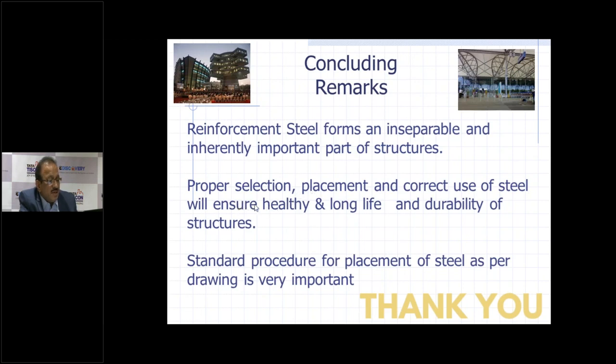Pushkar Patel wants to know, can we weld the bars instead of couplers? No, I will not recommend welding of the bars, because welding reduces the strength, and couplers can guarantee you the efficiency of the joint. In a particular column, if there are some 40-50 bars, welding each bar efficiently is very difficult; it is hard to control the quality and efficiency of the welding. So welding can be a risky solution, but couplers are a 100% foolproof solution. I would recommend that.